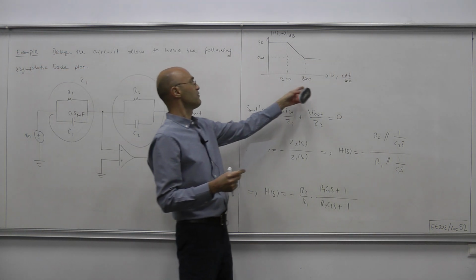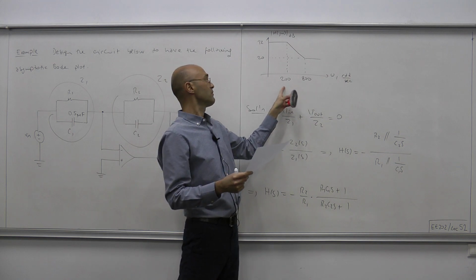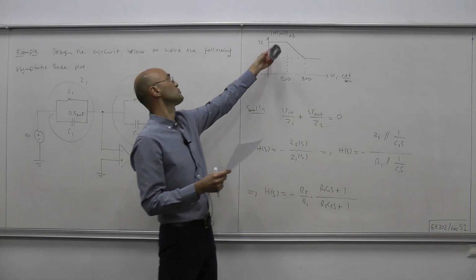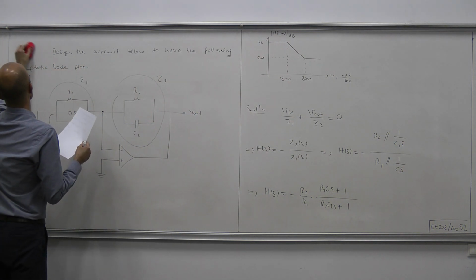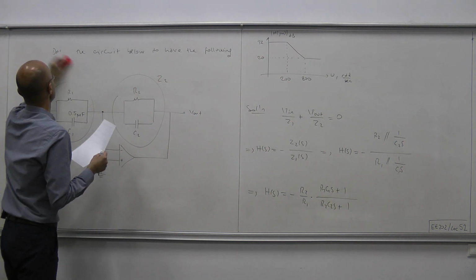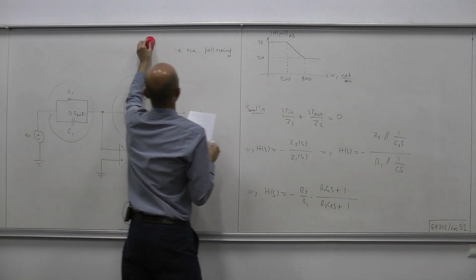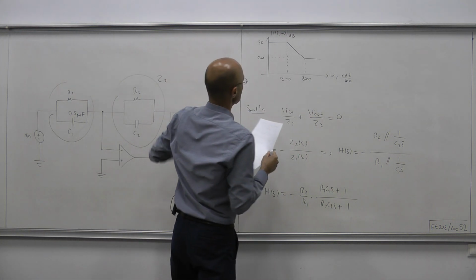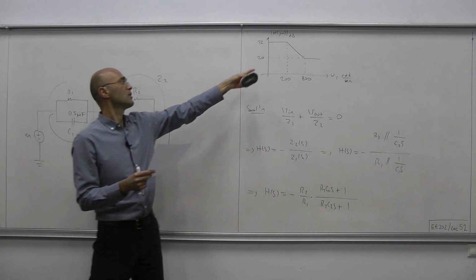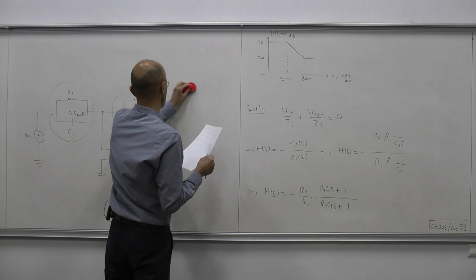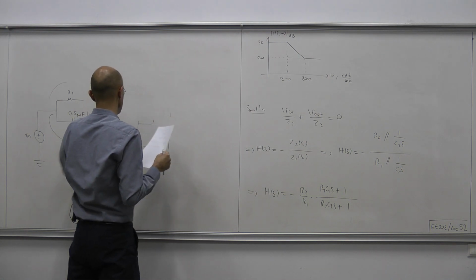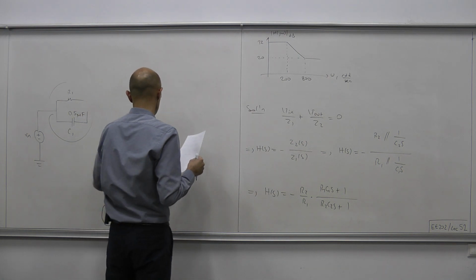And we know when the first order terms become active by looking at the Bode plot. We also see what the constant term will produce. And by comparing the transfer function and the information coming from our Bode plot, we will be able to easily figure out the missing parameter values.